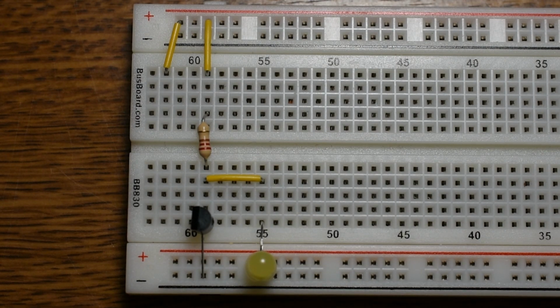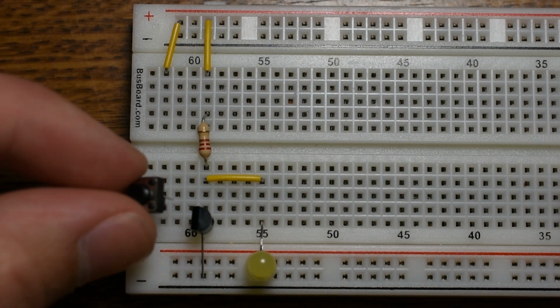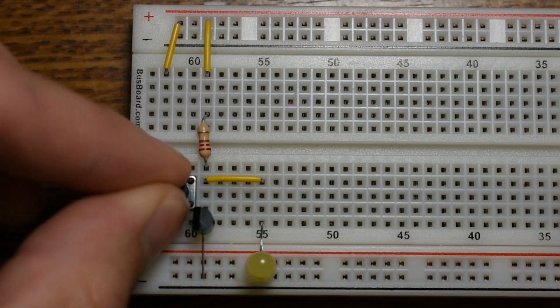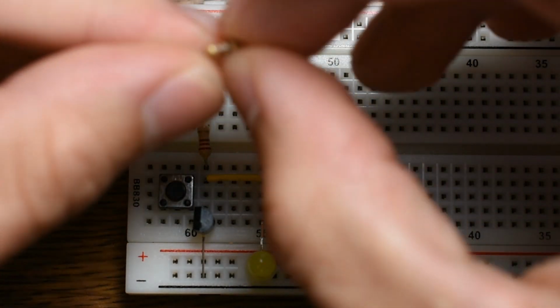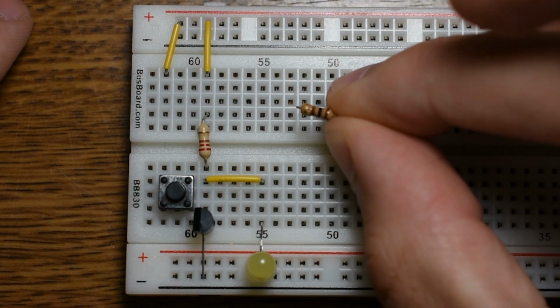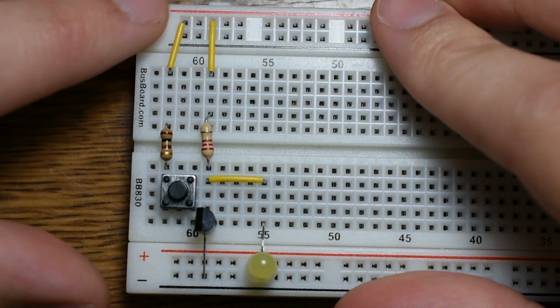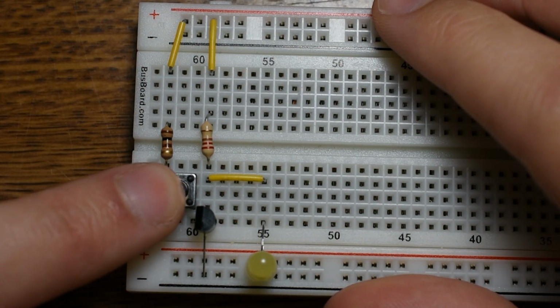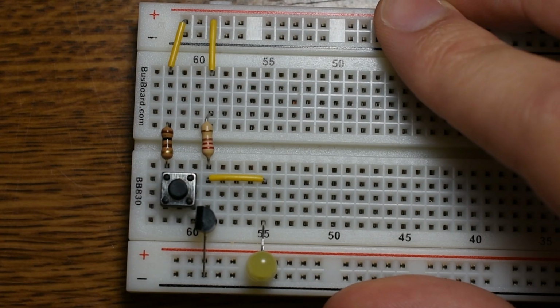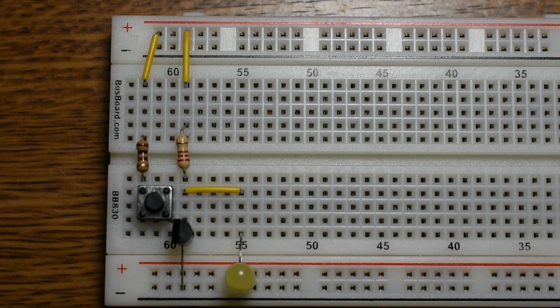And then to control the input, I have a regular button here. So I'll connect that to the base and to 5 volts as well, again through a resistor, which we didn't talk about, but that's so that we don't damage the transistors. So now the input is connected to 5 volts through a resistor and through a button. And when the button is pressed, we're providing a 1, and when the button is not pressed, we're providing a 0 to the input. And all we need is power.